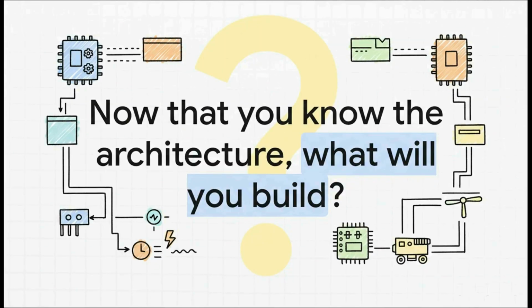So there you have it. We've toured the CPU core, we've navigated the memory map, we've traveled the data highways, and we've seen how to talk to the world and respond to events in real time. You now have the foundational map to navigate any STM32 microcontroller. You understand that it's all about enabling clocks, finding the right address, and writing the right value. The only question left is, now that you understand the machine, what are you going to build with it?